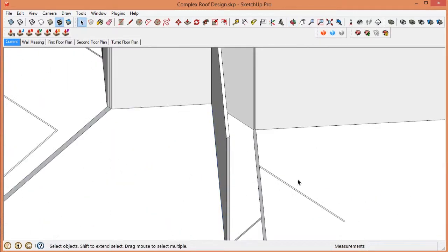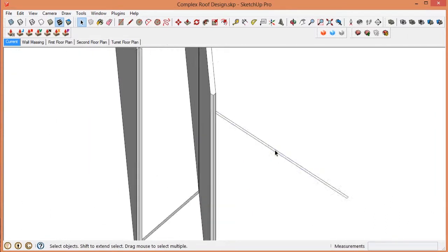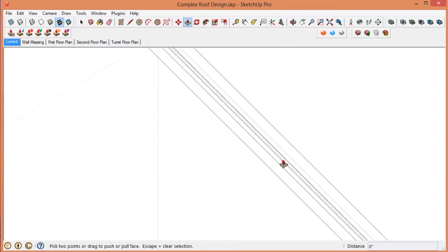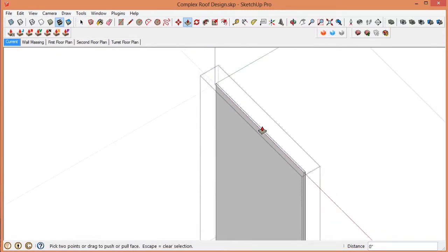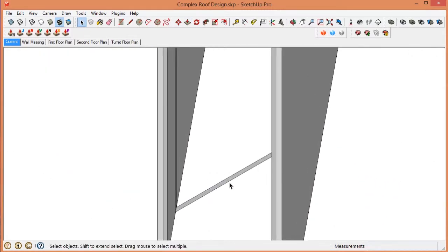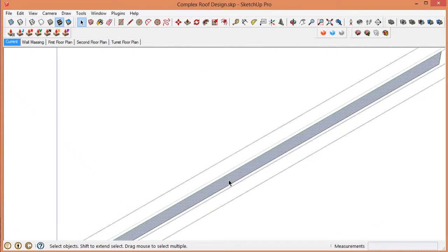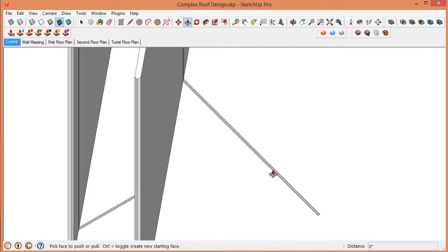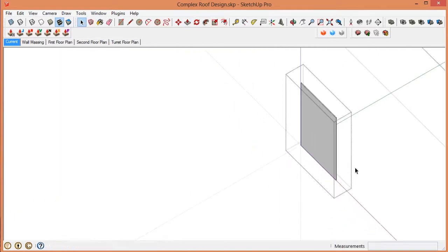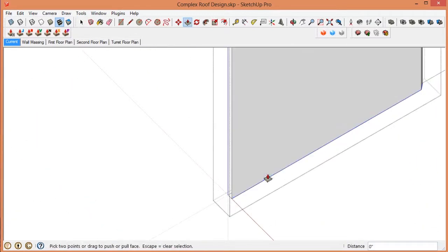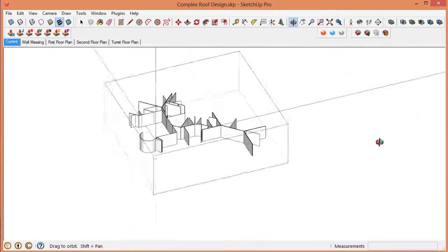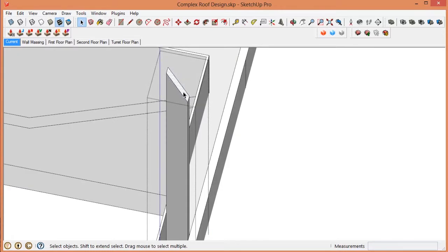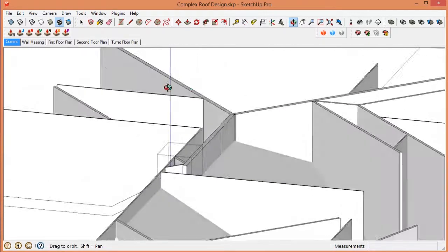One thing to keep an eye on is sometimes when you use the double-click method with the push-pull tool, it goes the wrong way. And that's typically because the face is reversed of what you had been doing previously. In this case, we had the reverse faces. They are dark. In this case, it was a normal face, which was not dark. And so the trick is to reverse it, and then when you use the double click on the push-pull tool, it goes the right way. There you have it. This one here is a little high. We'll trim it down, though it doesn't make any difference whatsoever.